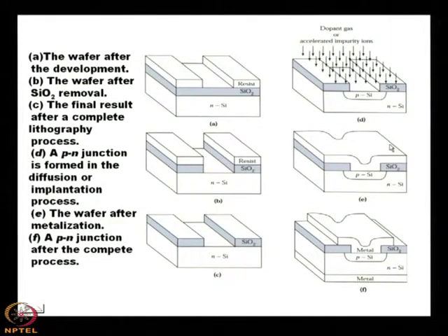Okay. Now, so far as the contact is concerned, generally the whole surface is given the metallization. It is done by the thermal evaporation technique, we shall discuss separately, and what type of metal we choose, why aluminum is chosen for silicon, why if you use gold or platinum it will be a Schottky type of contact, why those things happen, that we shall discuss separately.